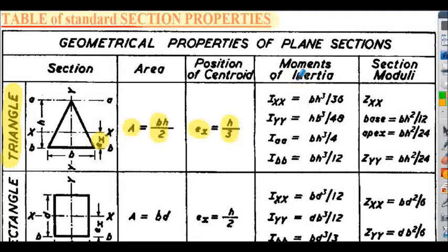Then notice in the next column we have what's called moments of inertia. In this case it's actually second moments of area. There's often a conflation between these two expressions. Moment of inertia in the past has been used to relate to second moments of area, but we should be definitive in our terminology, because within the same problem, for example a rotating mass on a shaft, we may have both second moment of area and moment of inertia to consider. To analyse the shaft in bending, we may use the second moment of area, but to analyse the rotating flywheel on the shaft, we will use the moment of inertia. So as we mentioned previously, they're different but related properties.